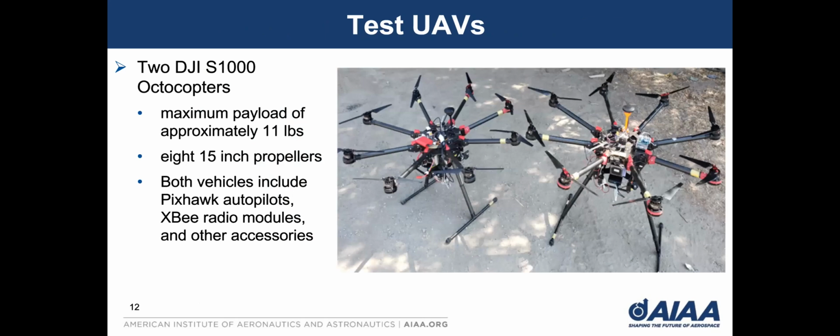The two test vehicles we're using in this project are DJI S1000 octocopters. The maximum payload is approximately 11 pounds, and each of them has 18-inch propellers. Both vehicles included a Pixhawk autopilot, SiK radio, and other accessories.